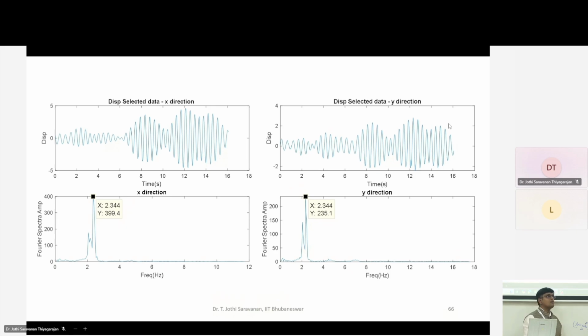Whatever we did, we were always focused on the structure which is flying over. We were happily standing on the pedestrian part of the road, placing my tripod and capturing the video. I understood that if my base itself is vibrating, that is possible. Maybe if you're standing on one bridge and capturing another bridge, and your bridge is vibrating, then it's better to have a sensor on the tripod, capture that signal, and subtract that signal. That's a simple thing that we do.